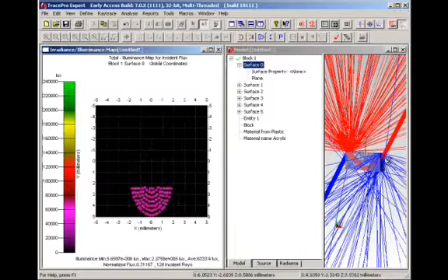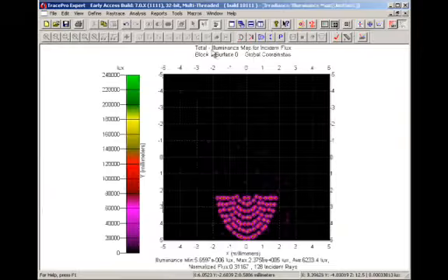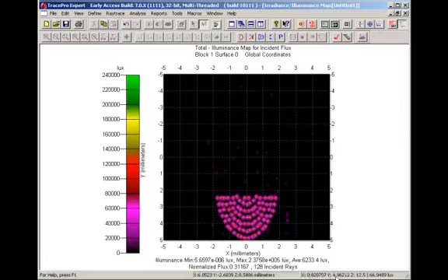We can see that that's exactly what's happening. We see the blue rays all the way around it. I'm going to now blow this back up again. You can see the small little amount of rays back here. Anywhere that you put the cursor, it will show you the XYZ location and the amount of power, and in this case in photometric units for those rays striking that surface. If you trace more rays, you'll get a much nicer distribution. And you can see over here on the left it has a scale of exactly how much lux is associated with each one of those rays.